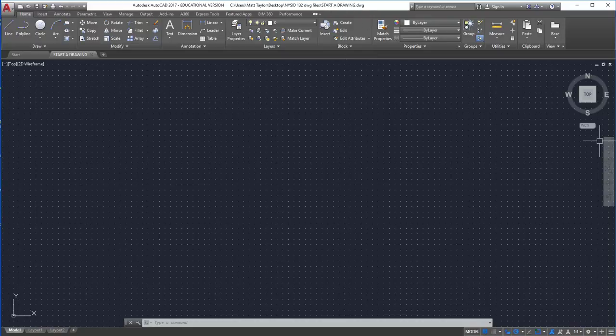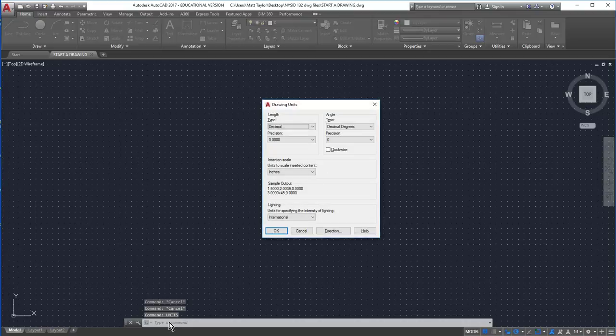Next, units. As I showed you in the previous video, you can draw in AutoCAD using many different types of units. If you type in the word units, a quick aside here, you don't have to click on the command line here ever. It knows, as long as it says type a command, that means you can type it anywhere. My cursor is up there, I just type units, enter. It's a good habit to get into. I see people many months in continuing to click on this command line. Don't have to do it.